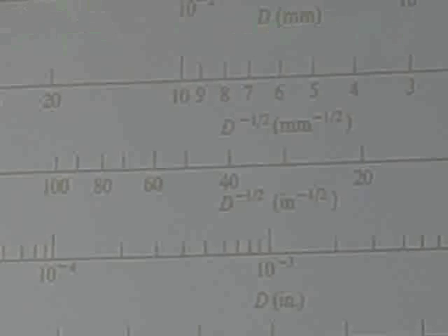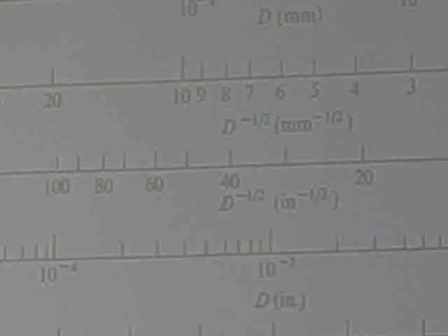So you can talk about D, the diameter of grains, in millimeters. You can think of it in D to the minus 1/2. That's the Hall-Petch equation. If you're a physical metallurgist, you know that finer grain sizes give you higher strength and higher toughness. This is in millimeters. This is inches to the -1/2. Here's D in inches. And then there's the ASTM grain size number. ASTM, really the steel guys years ago, came up with how many grains per square millimeter at 100x in a microscope or something. If you want, I could bring in the plates of the ASTM grain size.